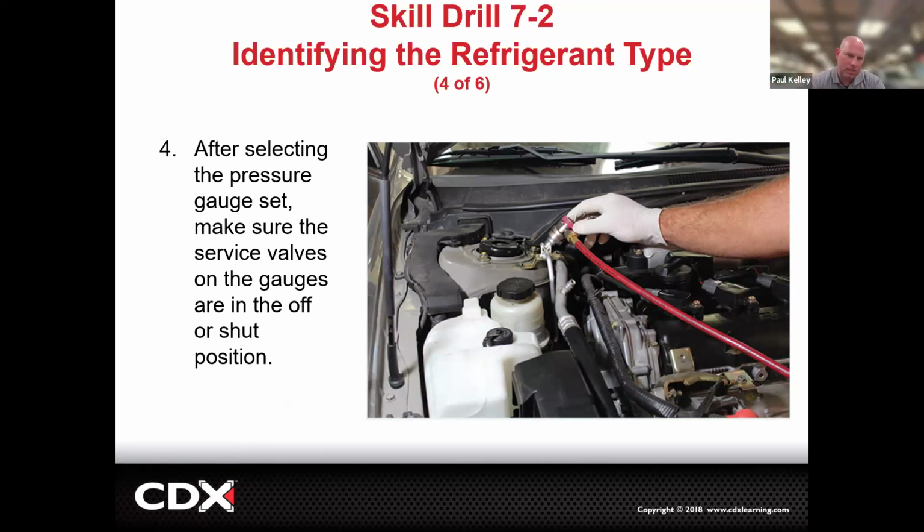This next step is actually determining what the refrigerant type is. This is something we wouldn't do real commonly where we're working on cars that are pretty reasonable. If someone is working on a car that just came from TJ, I'd probably take a second look at that car from TJ, because you have no idea what happened there. What happens in TJ stays in TJ, right? So if that car went down to TJ and the AC wasn't working, they very well might have put propane in there. They might not have had no R1234yf, but they got propane. Makes sense?